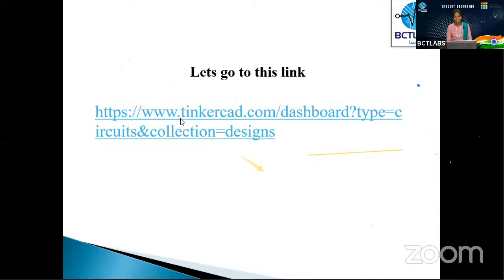This is what your Tinkercad dashboard will look like. You have to log in with your Gmail or you can log in with your class code. First I'm going to Circuits. In your dashboard you have to choose Circuits. Once you choose it, you can see an option called Create a new circuit. Click Create a new circuit.